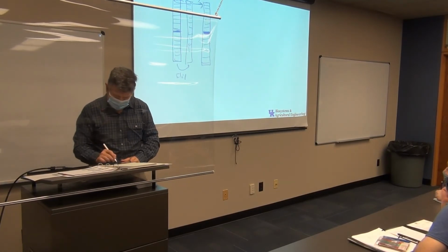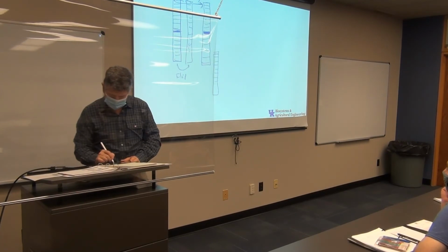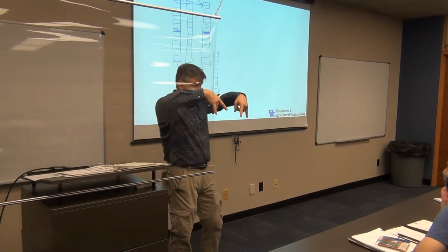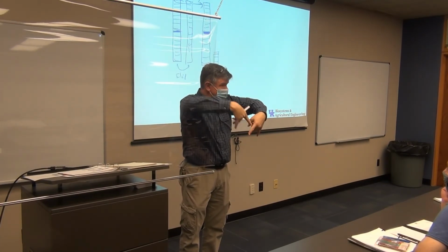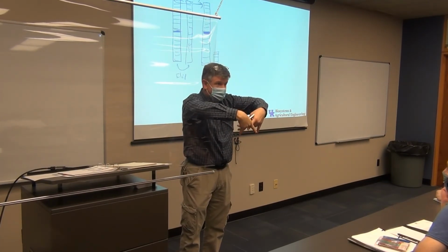So what I'm going to do then is take that same pattern, duplicate it, but pretend it's another nozzle pattern beside it. So basically that's what's going to happen. I'm going to have a second nozzle beside it on the boom, and some of that pattern from one nozzle is going to overlap with the pattern of the other nozzle.